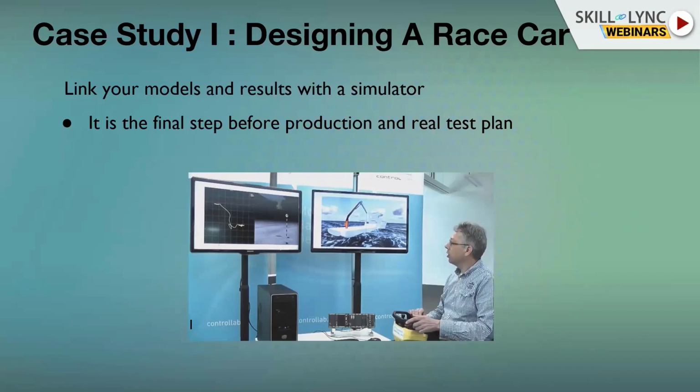So, for example, the car we developed with Dallara for the endurance program was tested on a simulator, and hence we had inputs for our Laptime simulations from the outputs of the simulator, and also we could add the driver model, I would say, because obviously Laptime simulation is a theoretical lap based on the best racing line and the best grip available, but you have to include a driver model, and this driver model is usually based on simulator outputs, because each driver is a bit different, and each driver has a different feedback as well.